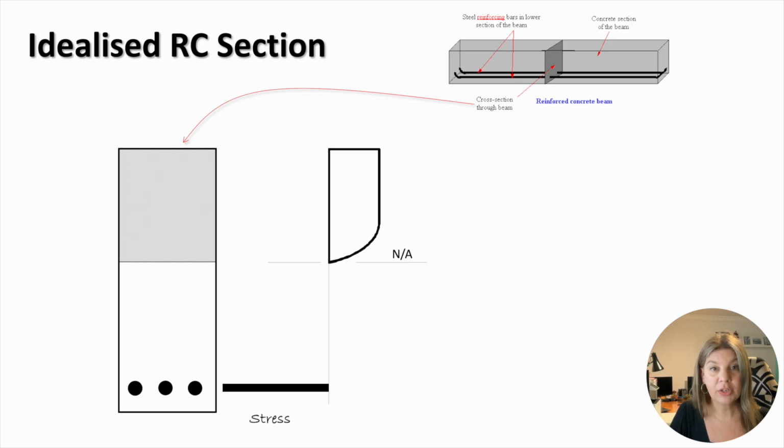Therefore, the concrete in the compression zone will have a distribution corresponding to an adopted stress-strain diagram. In the case shown here, the parabolic rectangular diagram is used. The distribution of stresses in the reinforcing steel bars is assumed uniform due to the relatively small bar diameters. Since simple beam theory is applied, the distribution of the strain through the cross-section is linear at every stage of the beam deformation. The location of the bars in the section is defined by the effective section depth, d.